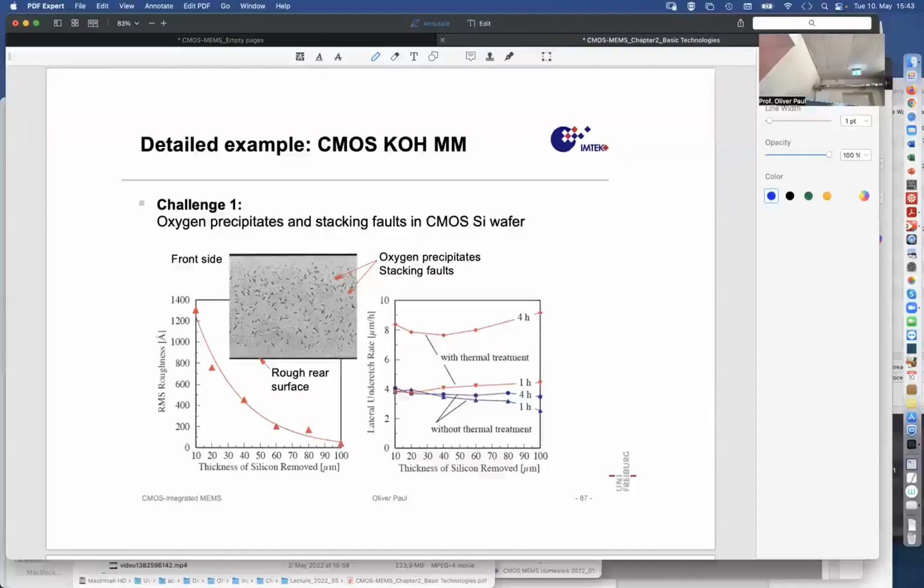At the surface, the oxygen is expelled by diffusion by the solution of the equation we have looked at today, because of a boundary condition saying there is no oxygen outside, so please diffuse out. And then there is this region, the so-called denuded zone, with little oxygen, in which the silicon is purer, and therefore a circuit can be built.